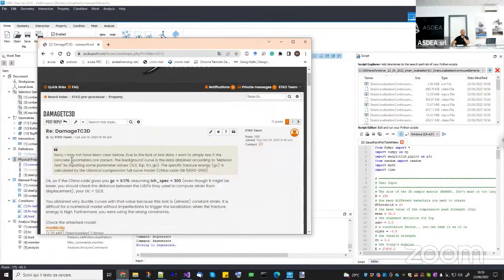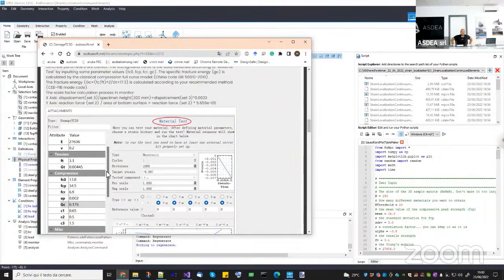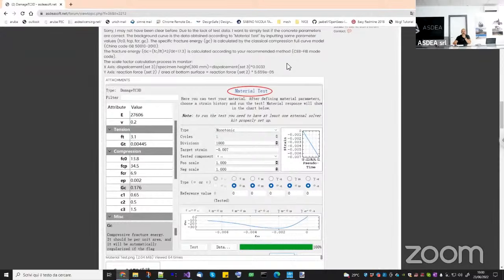by a user that was trying to model this kind of problem, and he asked all these kind of questions. I don't know if you noticed, but up to the first two examples that I've done before, I always assume that you have access to the real fracture energy. So sometimes it is true, sometimes it is not. Now imagine that you have some experimental test, and they give you the stress versus displacement graphs. So from those plots, you can get the real fracture energy.